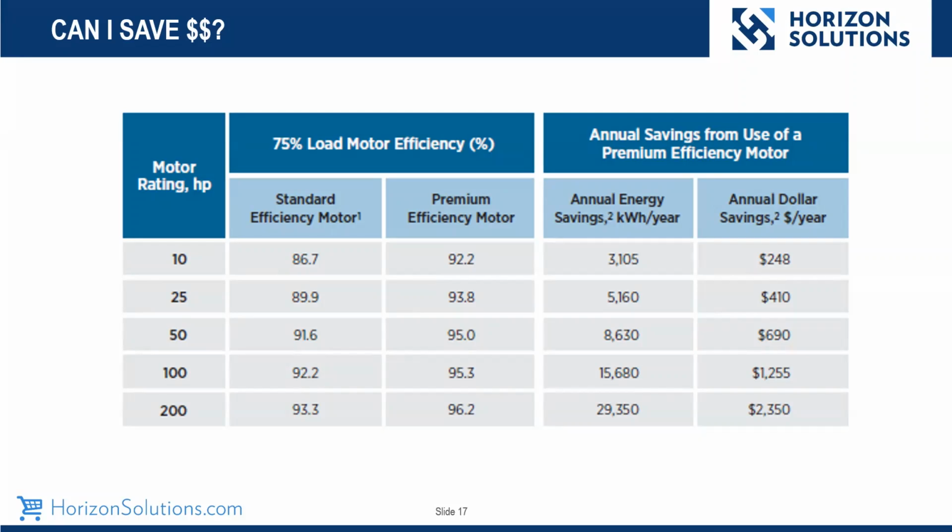You'll also see that, let's take an example, at 75% load, all these tests are done, and these are the percentages of them. You'll see in the premium efficient area that you do go up from a rating of around 92% efficiency to 96. So replacing these motors and not giving your money away to the electric company is probably a wise idea.